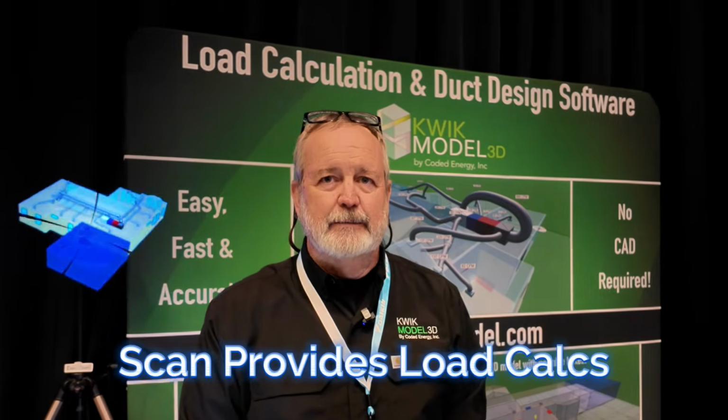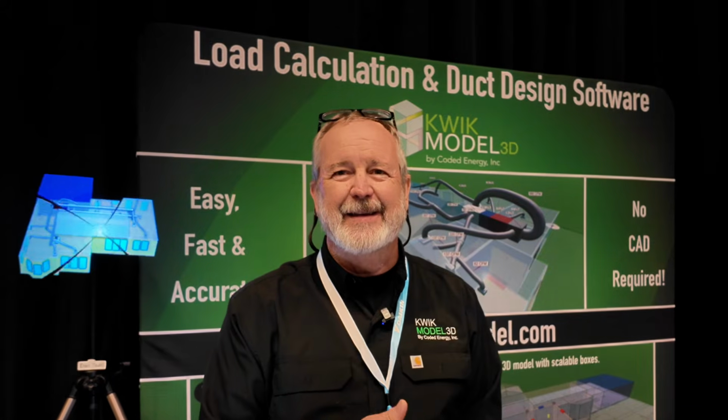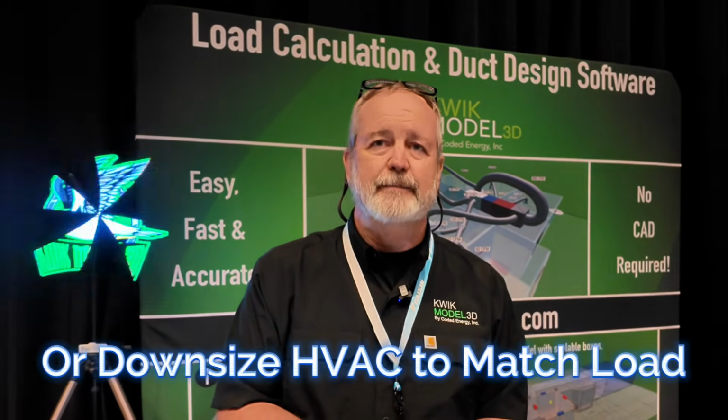So the scan gives you the heating, cooling load calculation. Yep. You can compare it to what the equipment is that you have in your house now. Yep. Know whether it's oversized, most likely. Yes. And then from there decide if you want to upsize ductwork or reconfigure things or downsize the equipment to match the load that you actually have.